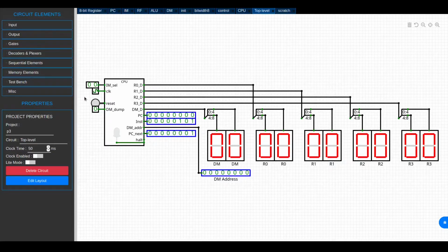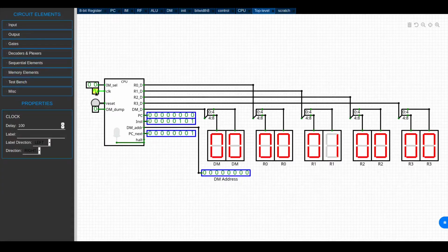This is test case V1 of the array width program. So when I manually run the clock, R1 fills with 1, R2 fills with 1, and R3 fills with -1. Then R1 and R2 are added together. The result is stored in R1, and then it is XORed with the -1 in register 3.